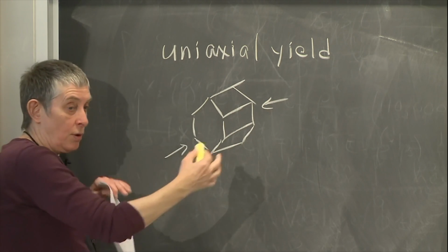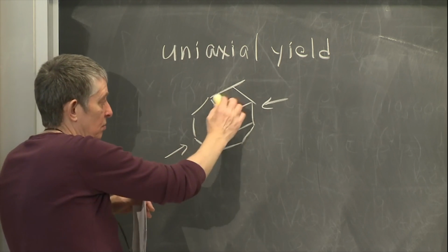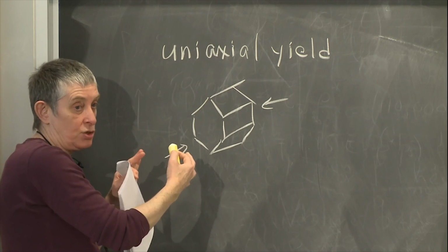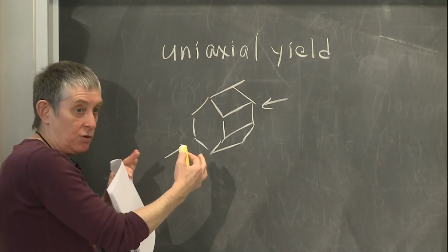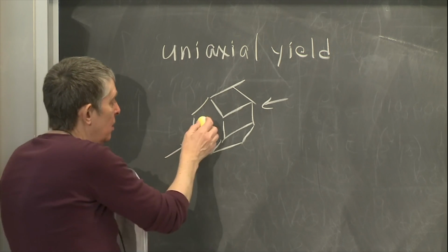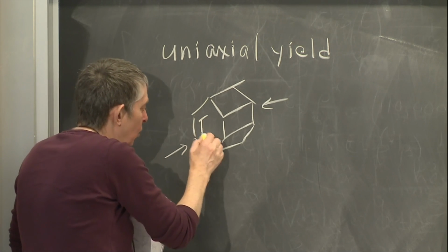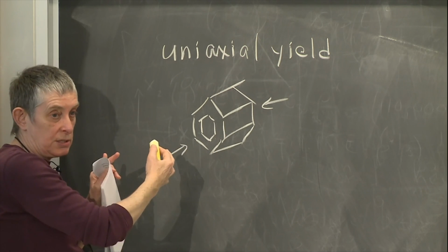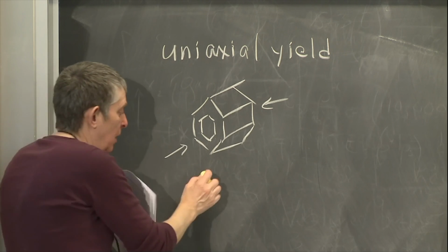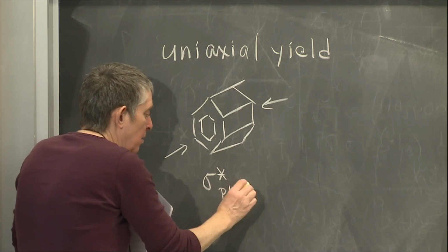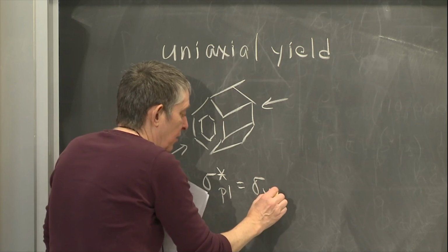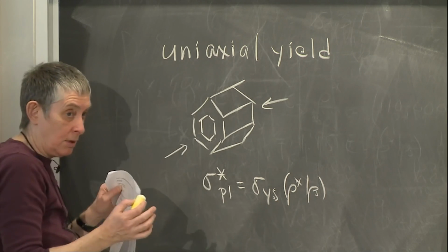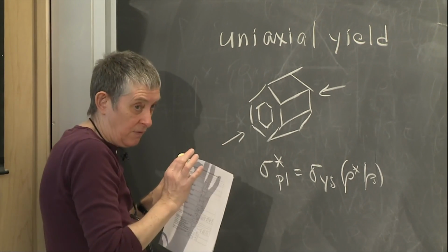The walls of the honeycomb are just axially deforming initially, so the elastic behavior is just axial deformation. If the cell walls are very thick, then you can reach a yield stress before any buckling occurs, and the strength would just be the yield stress of the cell wall material times the relative density. But the cell walls have to be thick for that to happen.